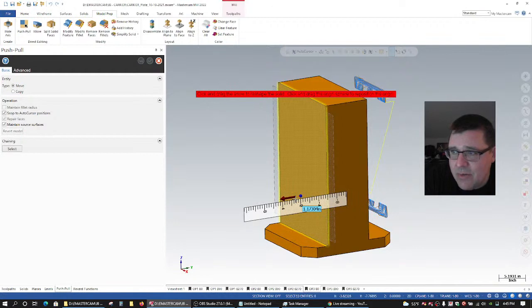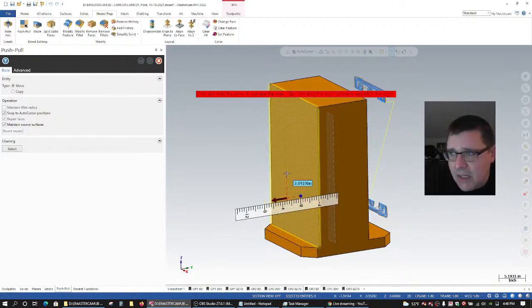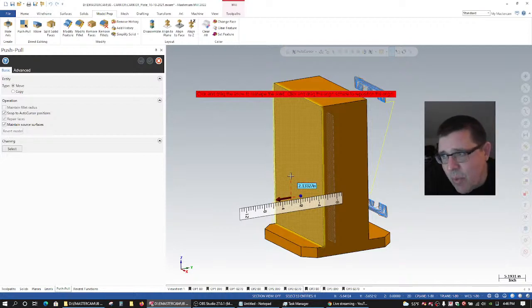And you'll notice when I do that, I get a slider bar that's got increments on it, but I also get the actual distance amount in a little data entry field that pops up there. Right now it says 2.13327. Once I go into the dragging command, so I'm actually dragging that face, it will respond to keyboard inputs.